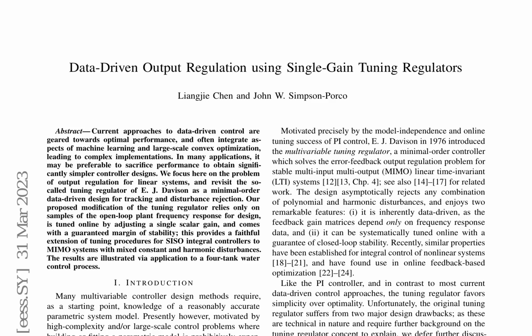It then formulates the error feedback output regulation problem as a design challenge for a dynamic controller that processes the error signal and produces control inputs, ensuring internal exponential stability and regulation of the closed-loop system. The paper underscores the importance of the non-resonance condition, which states that the transmission zeros of the plant must be disjoint from the poles of the servocompensator. This condition is necessary and sufficient for the existence of a stabilizing compensator solving the regulation problem.